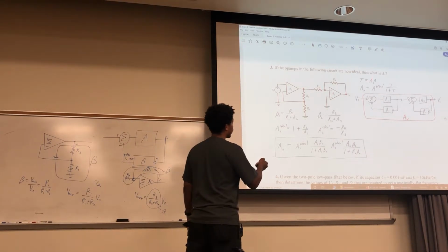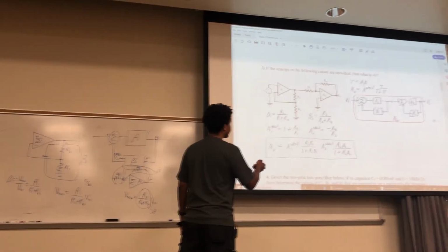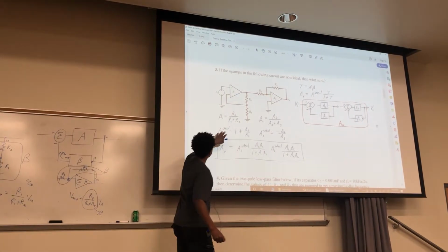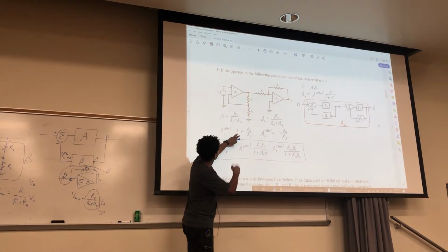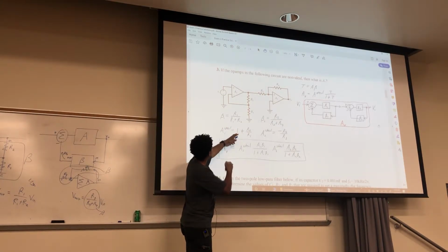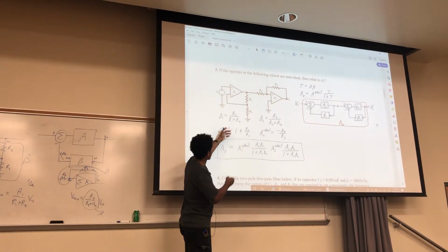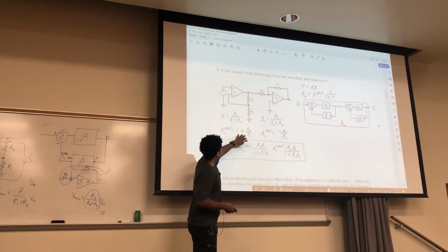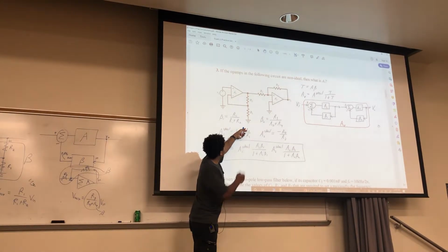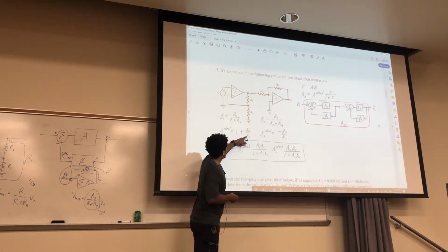That's what goes right here. This A is ideal, that's what this is, right? For this kind of structure, if it was ideal, where these two things were, there's no voltage difference between those two, no current going in, and all that good stuff. Then it's 1 plus your feedback right here over your R1.